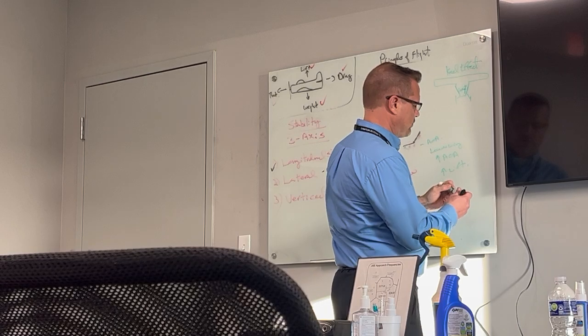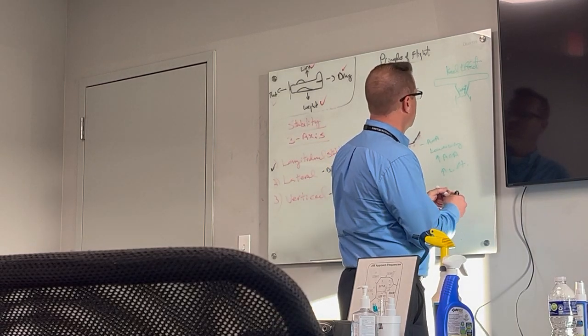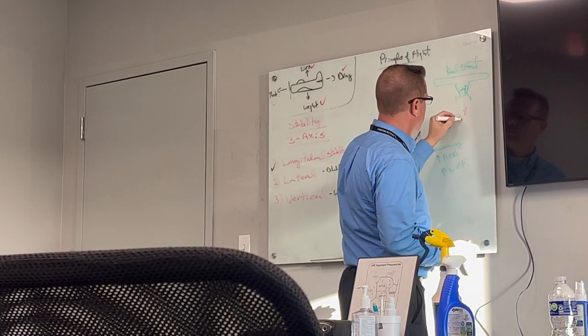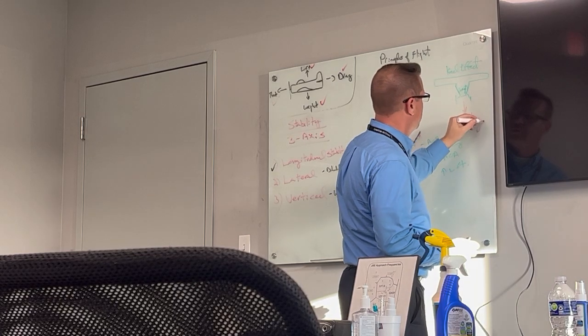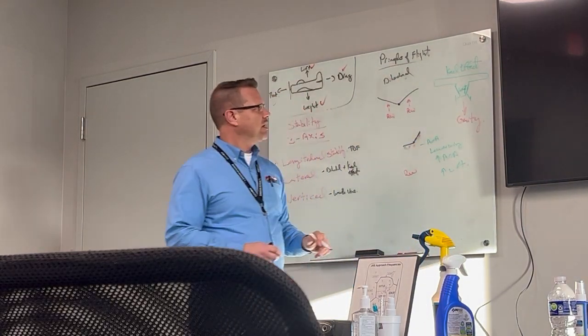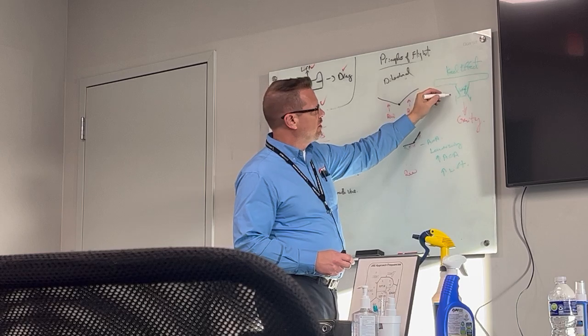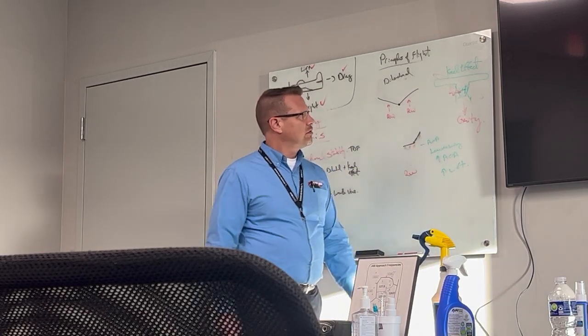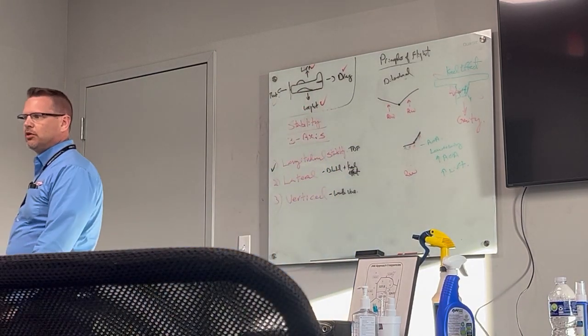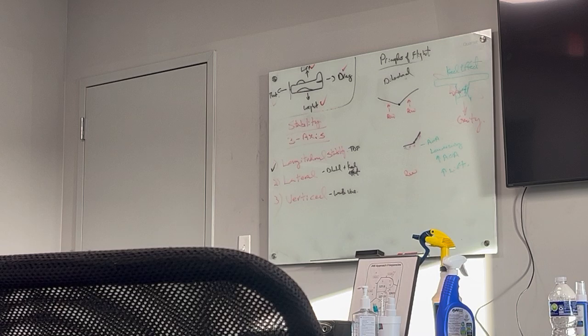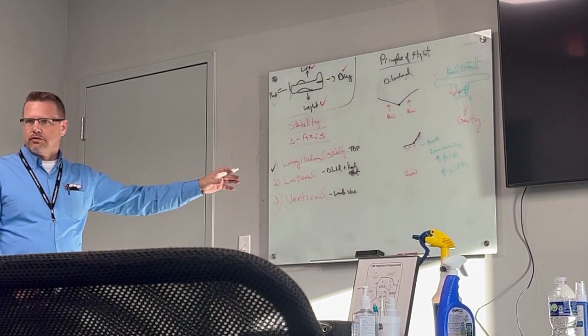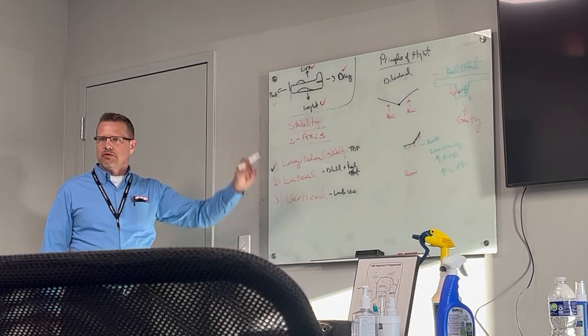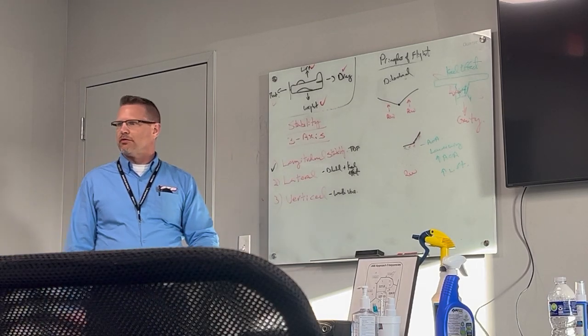It's because of the force of gravity, right? So gravity is always pulling straight down to the center of the earth. So if we bank that aircraft and we throw the weight off to the side here, gravity, of course, is just going to want to pull it back to equilibrium, or the center, right? By itself, just kind of like those marbles or whatever. If I pick it up, it's going to want to go back down. That would also be an example of keel effect.